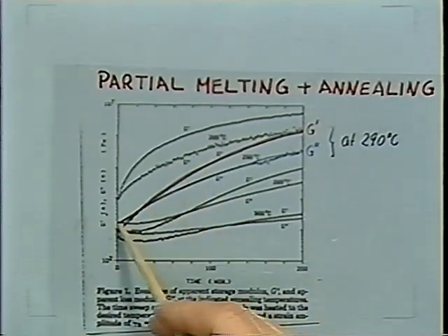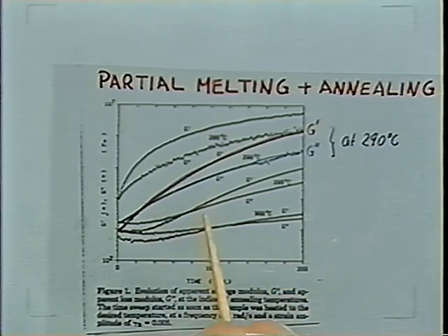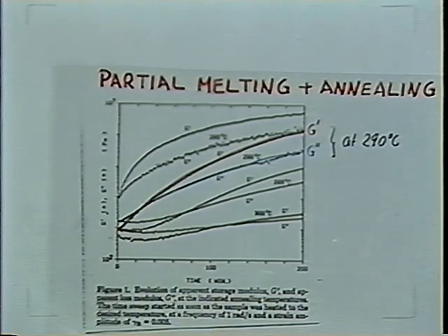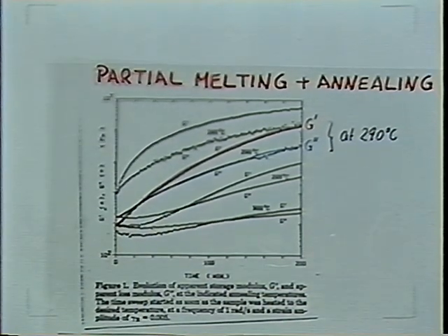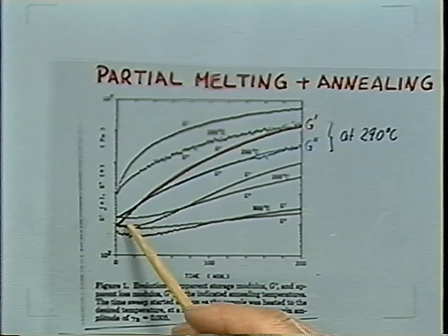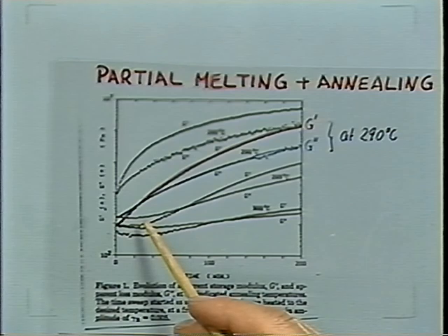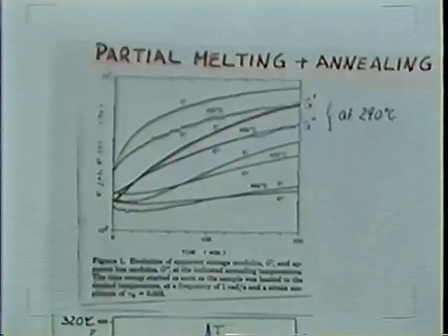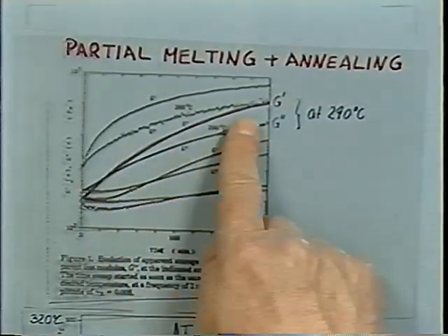The crystallization process starts very quickly. We say that this is a recrystallization process of this material. So it goes fairly fast because the nuclei are present. And secondly, the nuclei are of high order, and every addition to those nuclei, every growth, will be associated with a structure of high order. So the new material which we generate in this process has a much increased melting temperature. The melting temperature, in fact, increases by about 30 Kelvin in this recrystallization, and the order is much higher. There's a new ring coming in with the wax pattern. But let's move step by step.